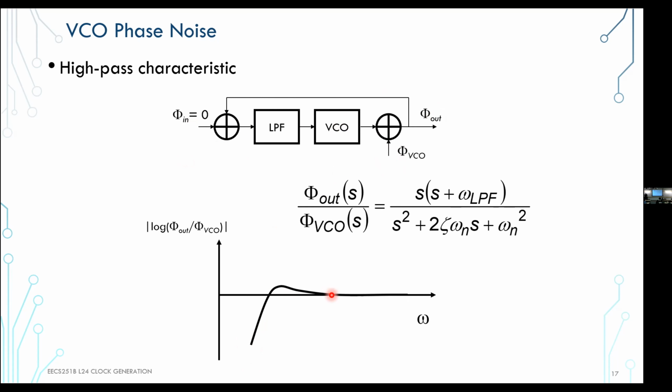What that means, in other words, is that if this was a disturbance with very low frequency, then the loop, because it's within the loop bandwidth, should be able to track it and reject it, because it really wants to match this to the clean reference, whatever it is, right? So that's exactly what's happening over here. Effectively any disturbance that you have in the output, the loop figures it out and rejects it, right?